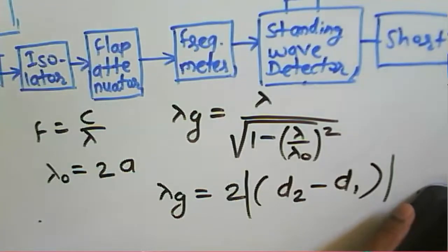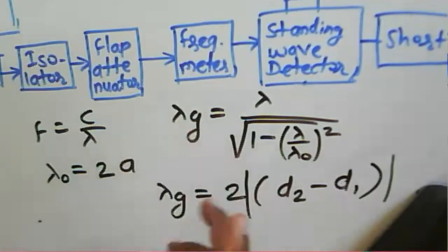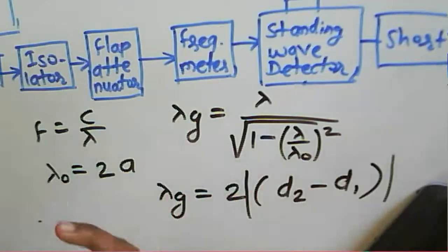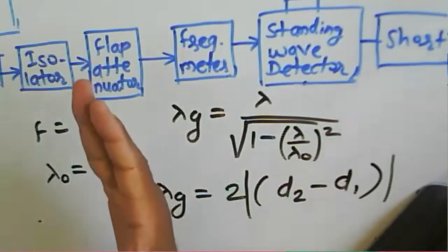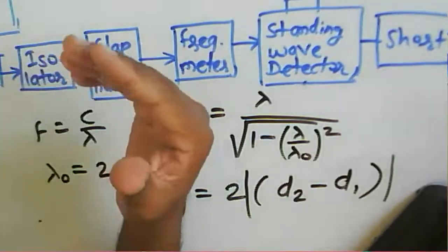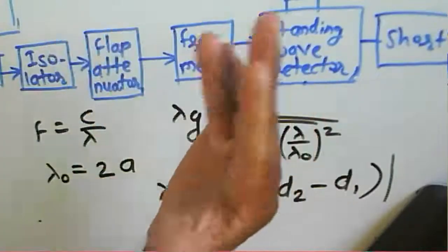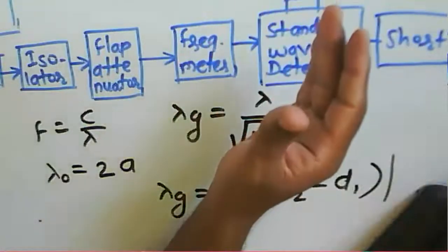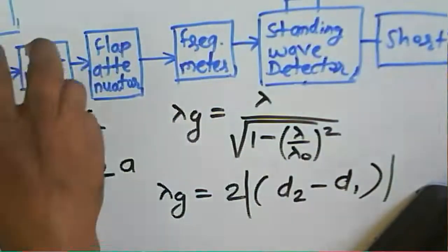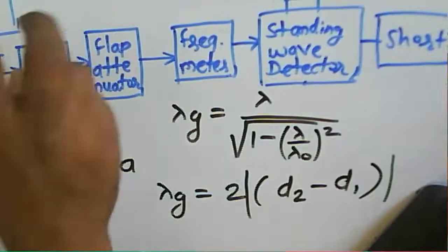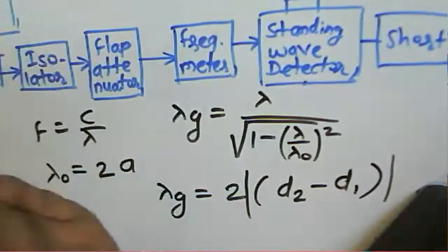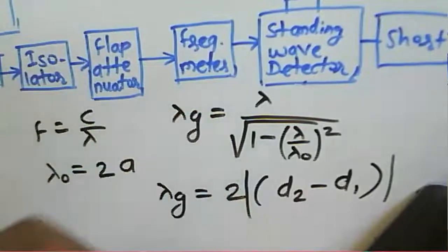We have seen today the measurement of frequency using the dip method. In the dip method, the wave meter is rotated in a clockwise or anti-clockwise direction. Wherever the input signal and the resonating frequency of the cavity of the wave meter match, we get a dip across the wave meter, and that dip is measured on the scale on the wave meter. The scale directly provides the frequency. That is the first method, the dip method.